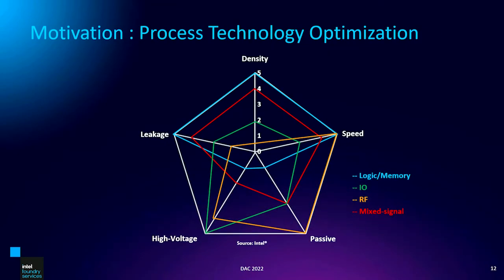Another reason we're going for chiplets as an industry is process technology is becoming highly specialized. So we see this across the world that, for example, I/O technology has thick gate oxide. Analog does not scale with semiconductor process. So what do we do? Well, we could create a chiplet with I/O technology such that it maintains thick gate oxide and doesn't benefit from scaling. So by segmenting that, we specialize the process. Another clear example is RF technology. RF technology is highly specialized. It needs passives and a lot of other stuff. With passive and RF technology, we see that becoming a separate chiplet.